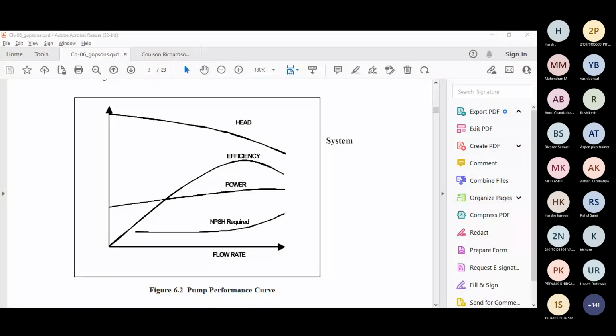अगर आपका जैसे कि पंप है, right? Suppose your pump suction tank is at the first floor, and your pump head is such that you can discharge up to 30 meters. अगर आपका पंप का suction first floor पे है, तो first floor से 30 meters, it is basically a differential head. If you put it at the second floor, it will pump 30 meters plus whatever the distance is. So the discharge minus the suction pressure, that is the head. It remains the same for any type of pump, right?